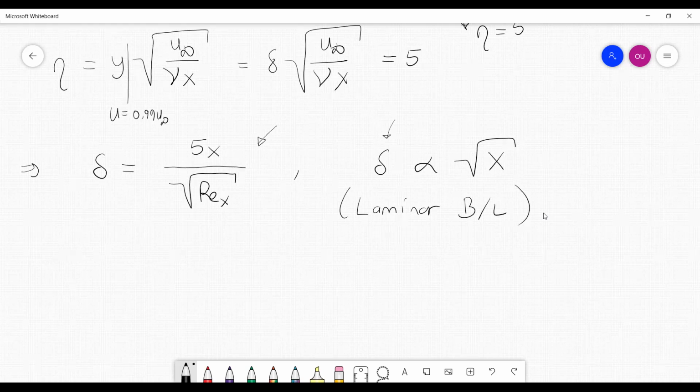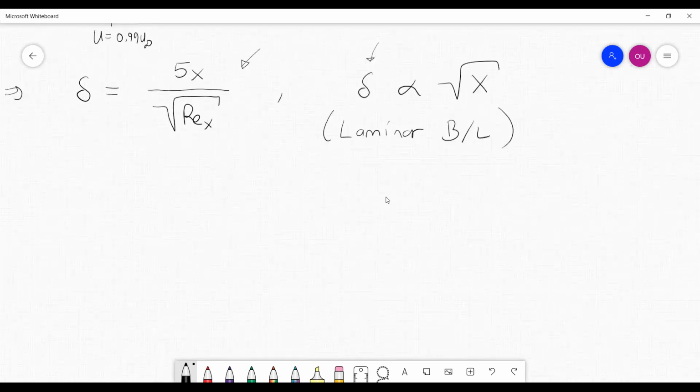So what else? Another parameter we are interested in is of course the displacement thickness, because we use the displacement thickness, as we have seen last week, for example for generating an effective body and implementing a hybrid implicit viscous solution and everything. So we need the delta star value.